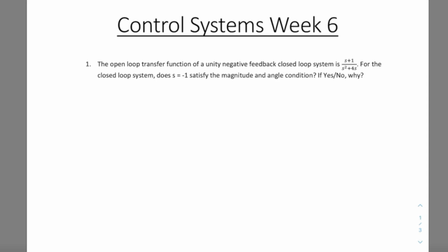And this week we will be discussing two questions about root locus. What is root locus? Root locus essentially helps us answer a question: how do the closed loop poles change when a system parameter is varied?